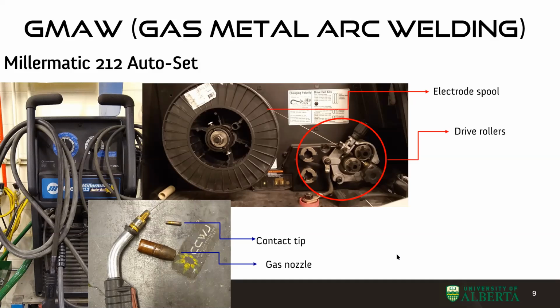In addition, we're going to see this later, but when the wire is feeding, it has a temperature distribution that is more or less linear from room temperature at the contact tip to some other temperature very near the end, and then a very big spike that reaches melting towards the end. But when you are starting, all the wire is at room temperature.